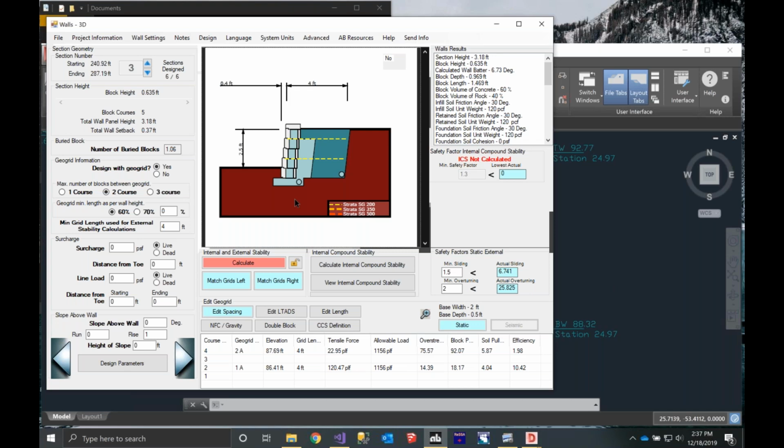And on sites where you've got slopes above and you've got slopes below, or you're in a seismic area or an area with very poor soils, all of those say that maybe or potentially you should design your wall based on a global stability analysis. And luckily, we have a great export into a global stability software that we use here at Allan Block called RISA Plus. So I'm going to quickly show you that.